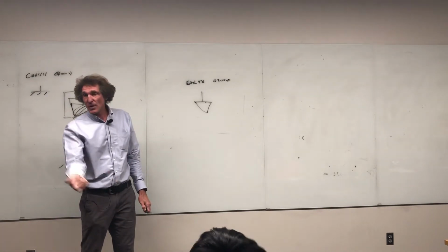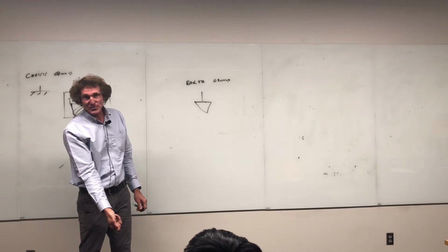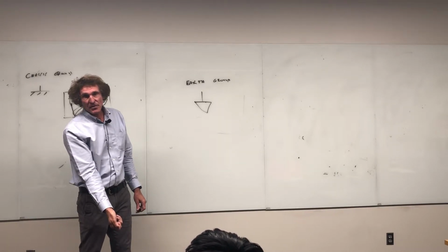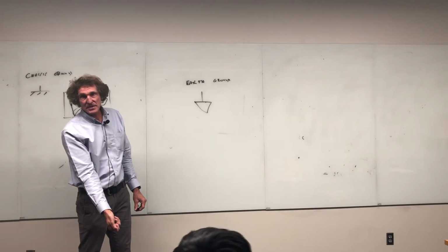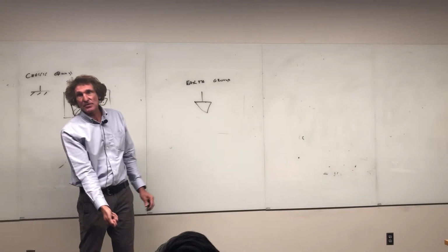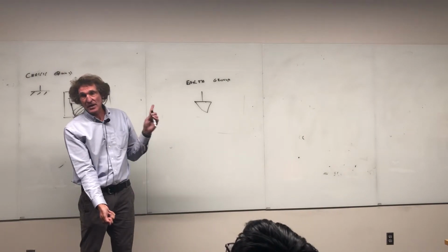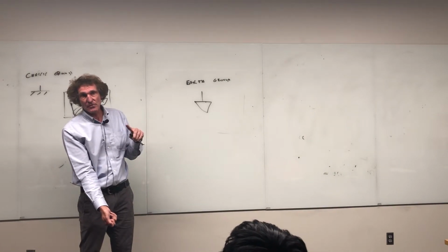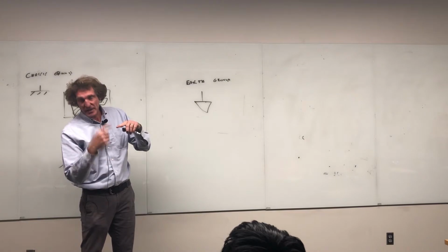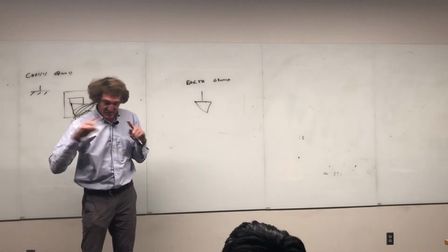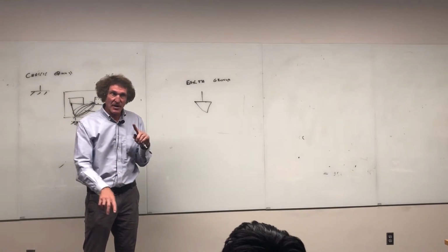And I don't know the gauge wire in Alabama that you're supposed to use, the thickest gauge, 2 gauge. The thicker the better. What that does is it assures that any signal where there's a fault in your house, this is going to come in from the power company, if it's shorted to that, it goes right to the ground and it doesn't route somewhere in your house and start a fire and things like this.